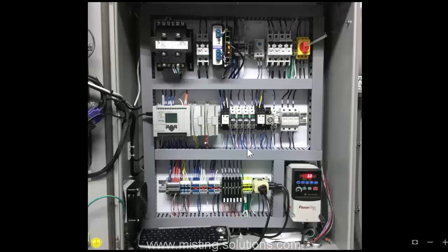Now, as the demand goes up, meaning that the DC level from the building automation system goes higher, those zone valves we just saw stage themselves on, 1 through 100%, every 10%. They stage on through the microcontroller, and when they do call for a zone, some solenoid valves, they actually energize these relays right here, 1, 2, 3, 4. So these relays stage on in sequence from 0 to 100%. At 10% you have one of them on, at 100% all 4 of them are on.